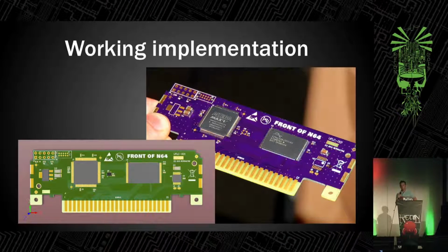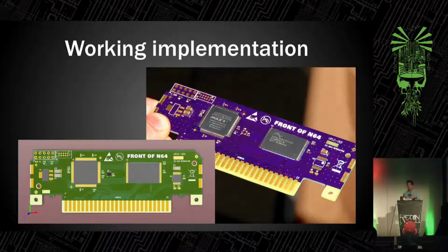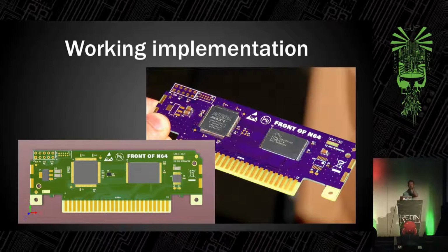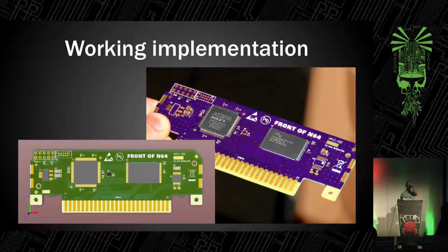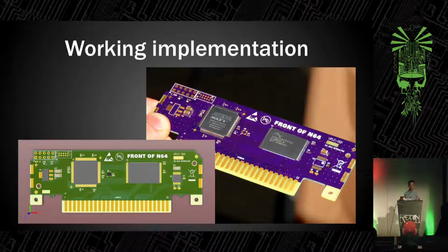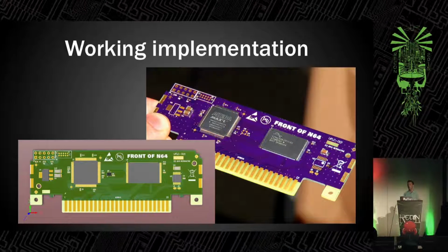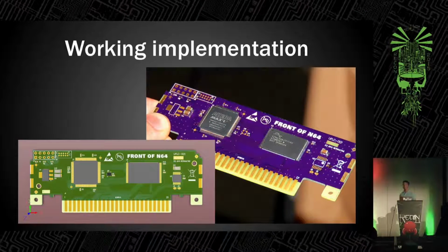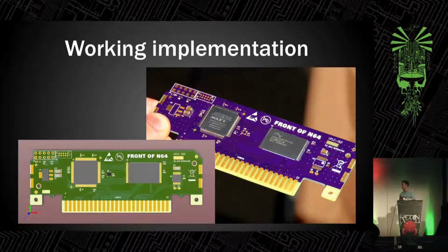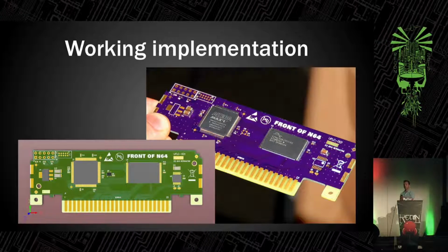So one of the other things I'm working on that's also related to Nintendo 64 is an HDMI converter that upscales the signal. So I needed a way to be able to update the firmware for that in the field. So I thought, okay, you just make yourself a custom game, you put in the Nintendo, it boots, and then it reflashes everything. So this is one of the biggest use cases that I can see right off for this CIC clone chip, is that you just put one on there, it costs like 70 cents, and then you can make scads of these things and not have to worry about getting them back. So you're not dependent on scavenging stuff from older games.